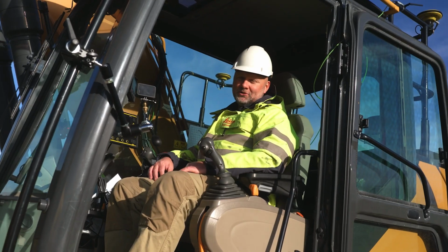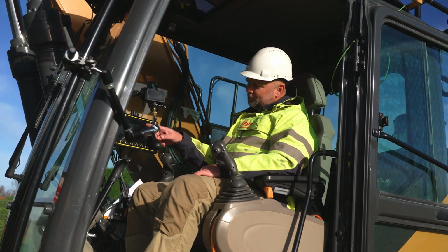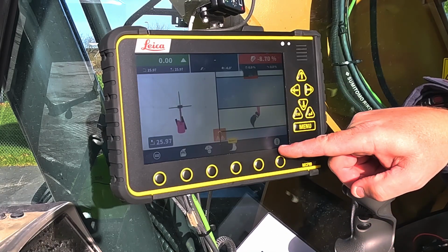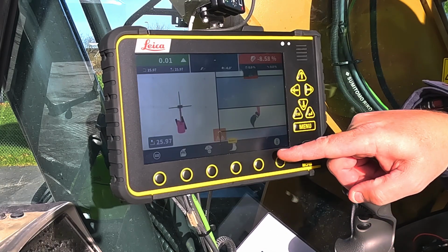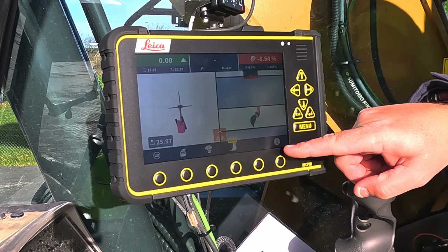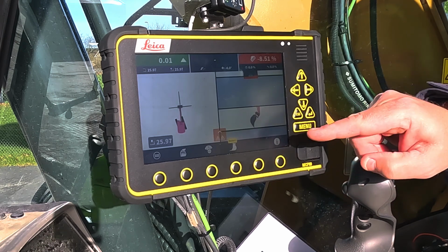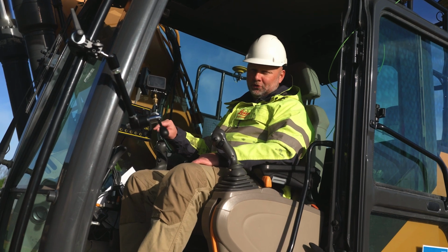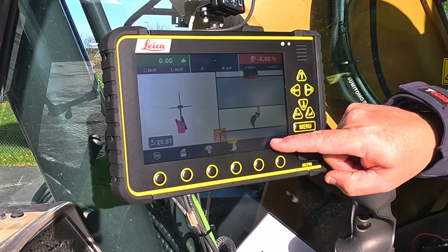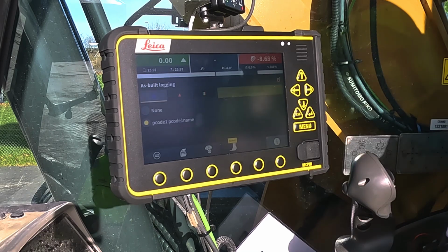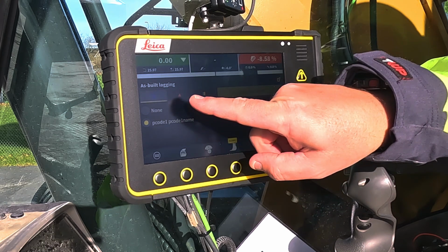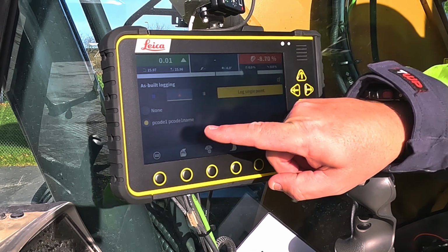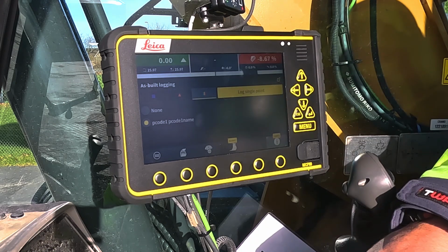If we now look in the machine on the panel, from the run screen where it's working, he has a button in the bottom right-hand corner with a small arrow on. And the button itself, that is your logging button. But to do the setup of what and how you want to log, you press and hold on that icon, and you will have 3 different options here. Either single point logging, auto point logging, or surface logging.